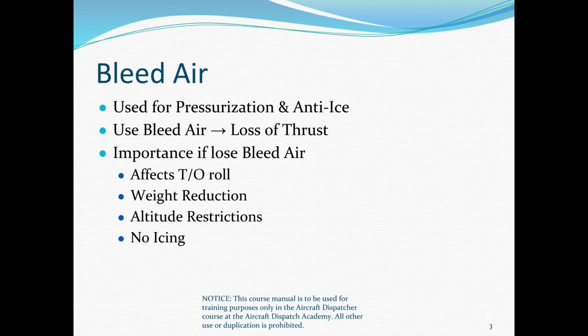So, could have a weight reduction, could have altitude restrictions, and then the biggest one that really affects us as dispatchers: what if one of our anti-ice systems is inoperative? Well, all of a sudden we have what we call a no icing aircraft.